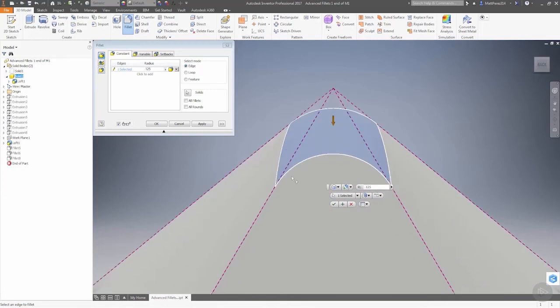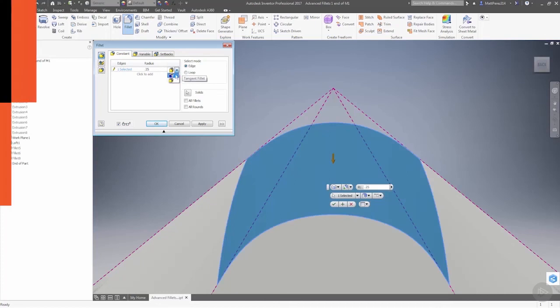As we look at this, the fillet has tangency on both edges. And because the angle is different on the faces from the start to the end, the fillet is actually wider on the back side than it is on the front side. Now if we change this to have a smooth continuity, it changes the shape of the fillet. In this case, it doesn't look that drastic, but it is actually making a big difference. If we make this fillet value larger, the difference will look a bit more.